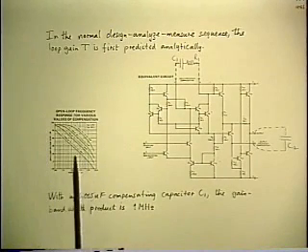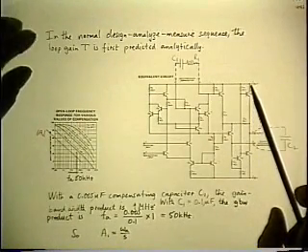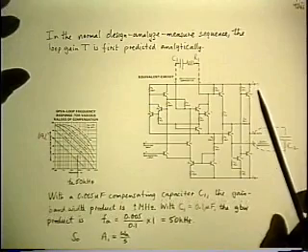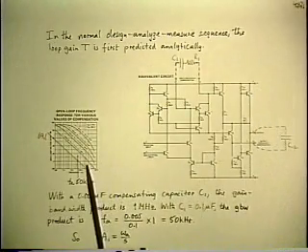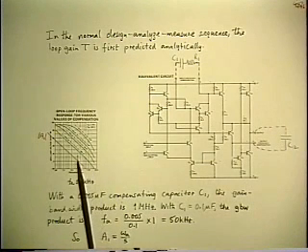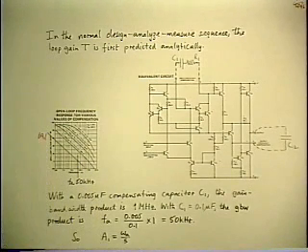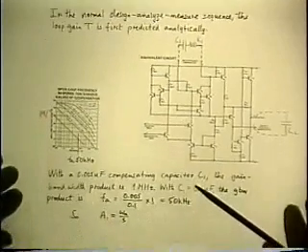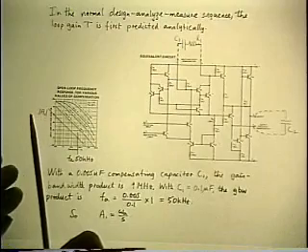But that's okay. If I'm using an even bigger capacitor, all I have to do is scale it down by the factor of 20, and that will change the unity gain frequency from 1 megahertz down to 50 kilohertz. And the pole at low frequencies has moved even further off, but according to the same argument that we've talked about several times, I don't even care where that is.